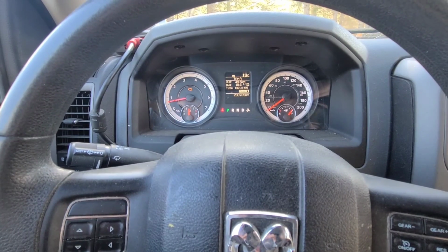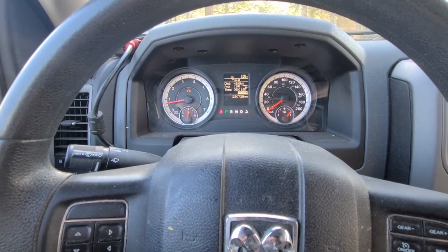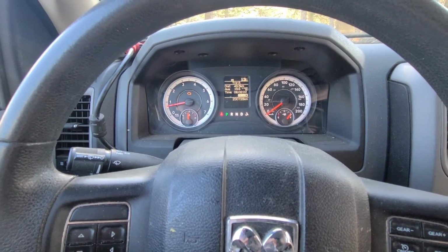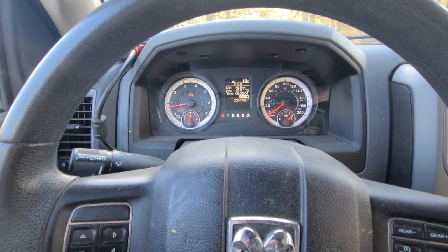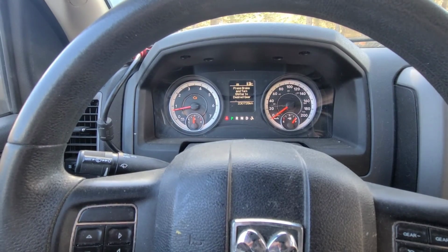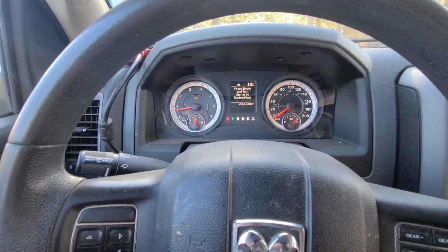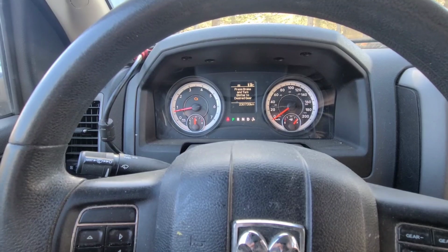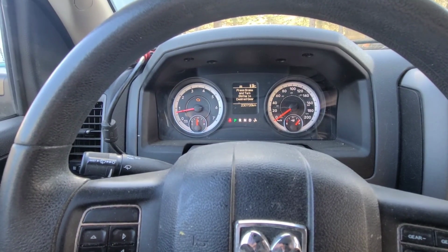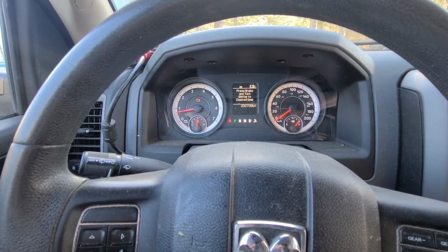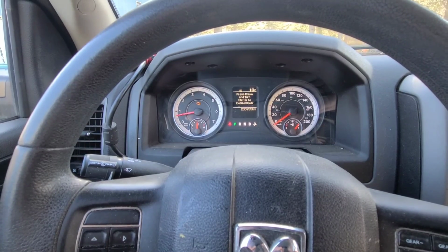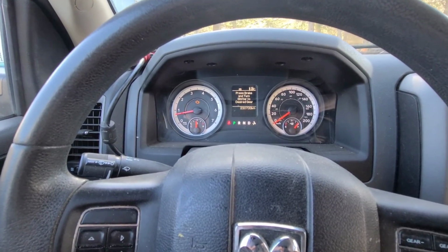Well, I just got back from about a 15-kilometer road test. Truck runs good. Check engine light is on because of that three-way valve being disconnected. It doesn't appear to affect drivability at all. But if it shorts out the 5-volt reference, it takes down APP2 and potentially one of the throttle position sensors too, if I'm not mistaken. So I'm leaving it disconnected. It's going to be about a week to get the new sensor or the new valve, and it's covered under a parts warranty, believe it or not.